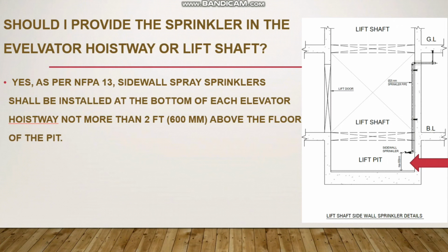And here we have the lift door, and this is the basement level or finish level, and here you can see I have taken the 25 mm sprinkler pipe, as I mentioned, from the ceiling till the bottom of the lift pit.